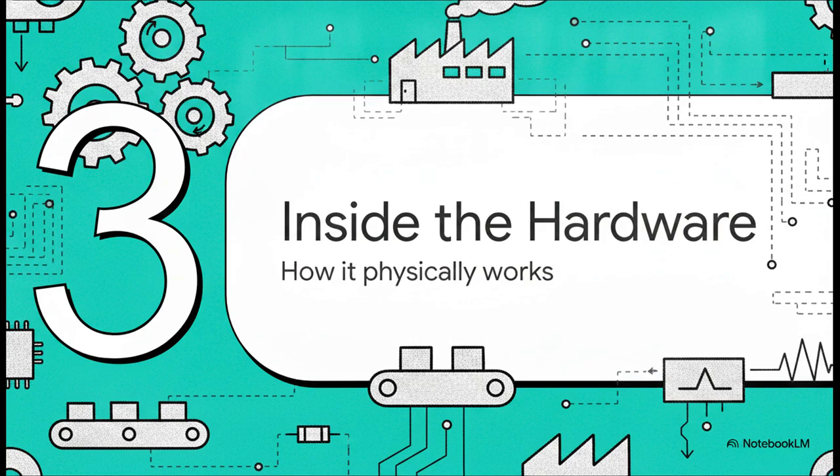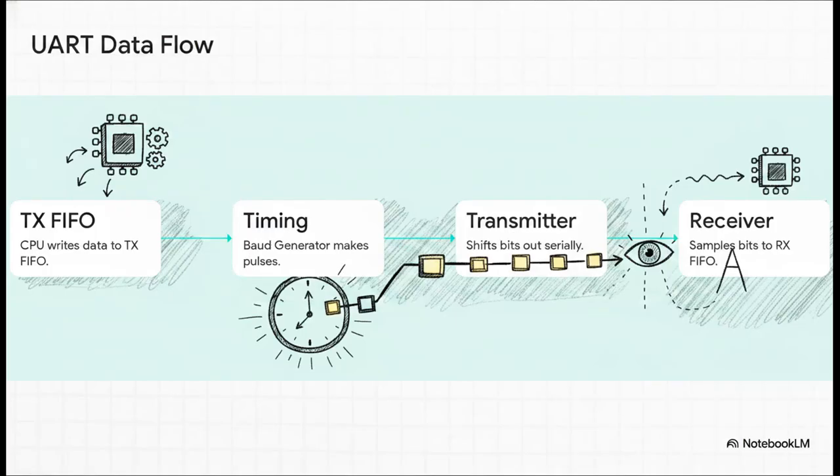Let's look at how this physically works. What does the factory inside the transmitter actually look like? Think of this whole flow like an automated assembly line. First up, the CPU drops the data off, but it can't just toss it haphazardly onto the wire. A highly accurate block called the baud-rate generator creates these incredibly precise timing pulses. Then, the transmitter hardware takes the data, adds our start and stop bits, and shifts it out serially onto the wire, perfectly timed to that baud rate.